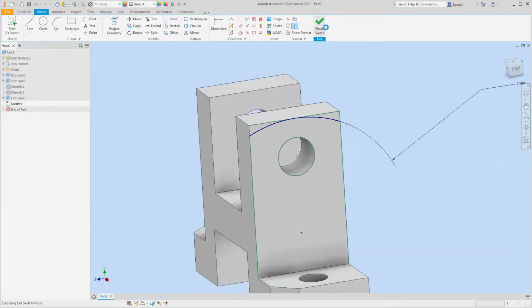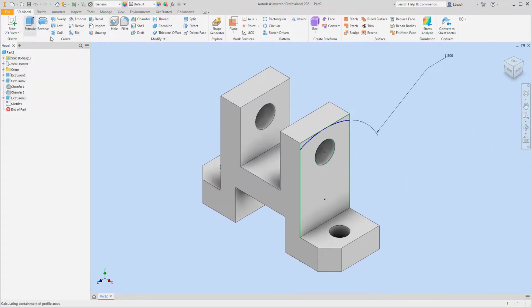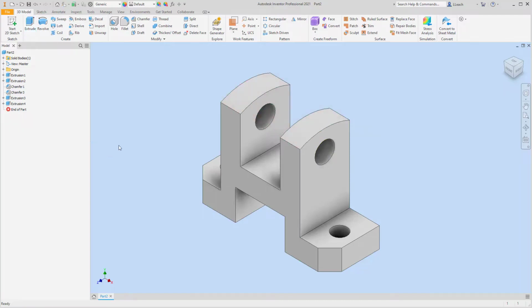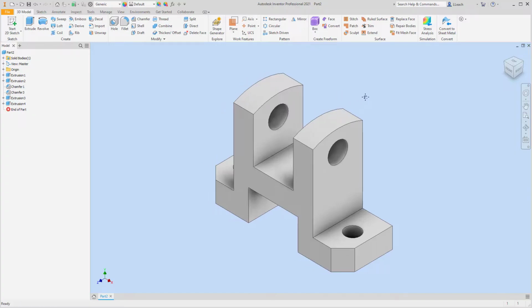I'm going to finish my sketch. I want to see if I can extrude cut the tippy top here and the tippy top there. And I want to cut it all the way back through all, like so. It kind of shaves off the top there. So yeah, that was a little tricky, a little challenging, but there's different ways you can do that. But, you know, that worked.